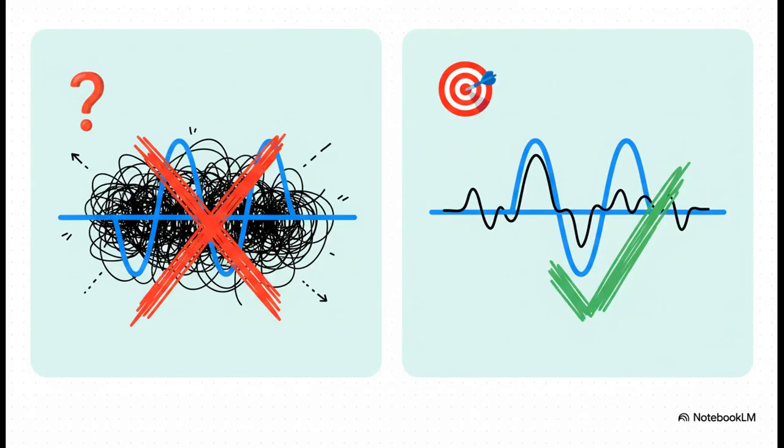Okay, now this is the real kicker. This slide points out a massive misconception. We all tend to think of this kind of interference as just random noise, you know? Something that just raises the noise floor a bit. But that is not the whole story. The really crucial point here is that when digital signals crosstalk into an analog path, that error isn't random at all. It is a predictable, deterministic error that is directly dependent on the original signal itself. And that fact completely changes how we troubleshoot it.